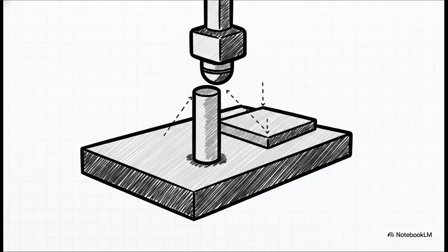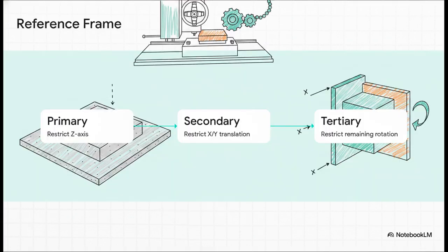So, how do we bridge the gap between perfect theory and imperfect reality? Well, quality inspectors rely on datum simulators. We're talking about high-precision physical tools here, like those perfectly calibrated granite slabs, gauge pins, angle plates, or even computer-generated planes from your CMM. These tools are used to physically simulate those theoretically perfect datums right there on the shop floor. And when we use them together, we establish a datum reference frame to completely lock down a part's 6 degrees of freedom in 3D space.